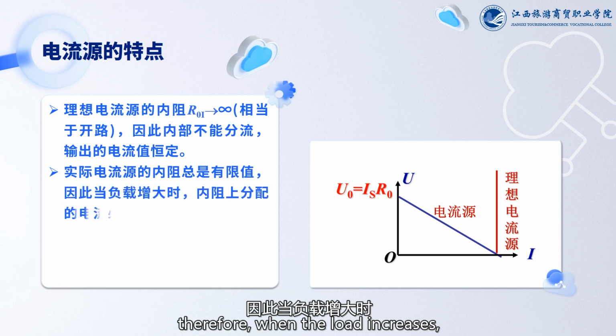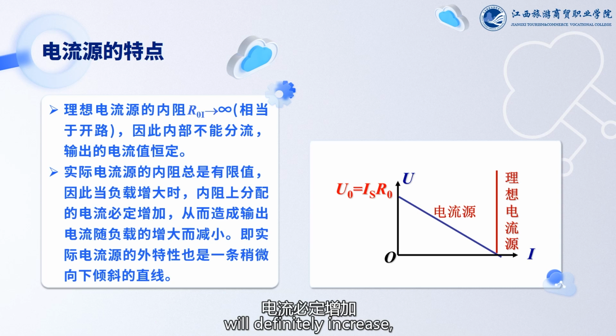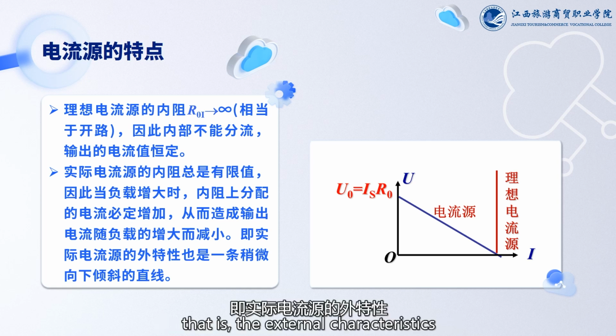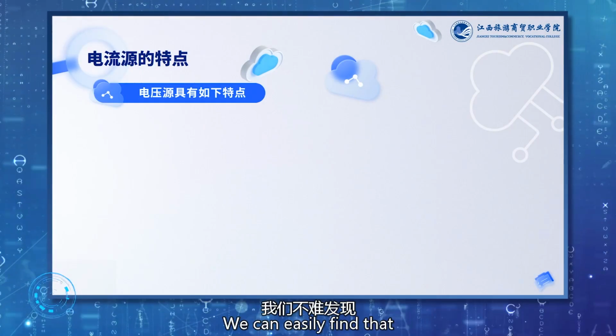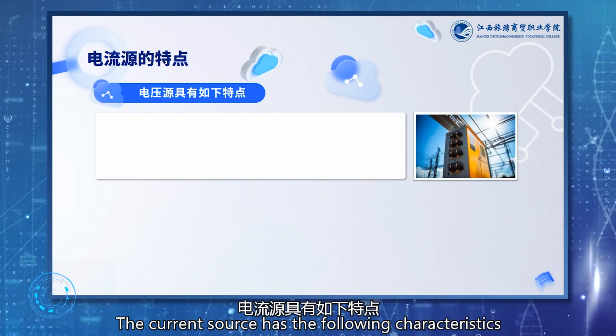Therefore, when the load increases, the current distributed on the internal resistance will definitely increase, resulting in the output current decreasing with the increase of the load. That is, the external characteristic of the actual current source is also a slightly downward inclined straight line. We can easily find that the current source has the following characteristics.